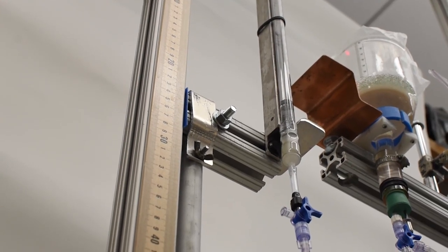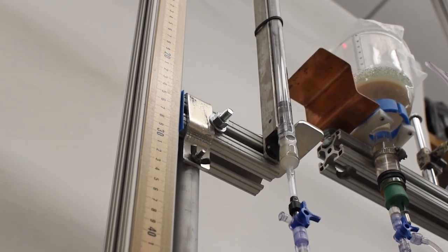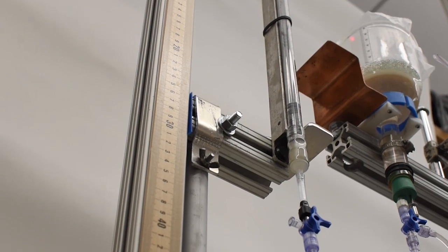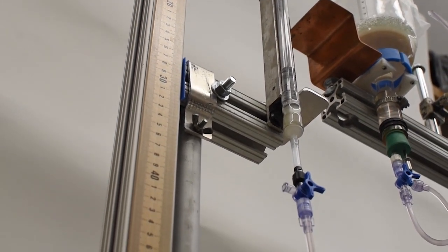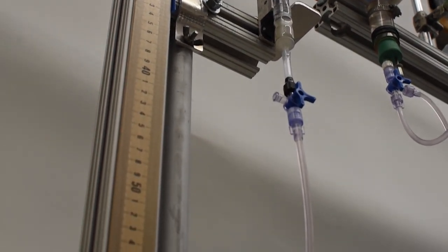The water volume is used to compute the volumetric water content. We now have a pair of volumetric water content and matric potential. The system then lowers the burette level to measure another pair at different matric potential. You can specify the stepwise increment in the program. The same procedures are followed, such as measuring the burette position and the pair of the matric potential and the volumetric water content under equilibrium condition.